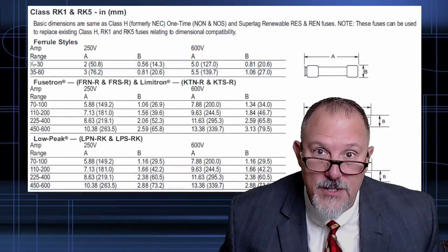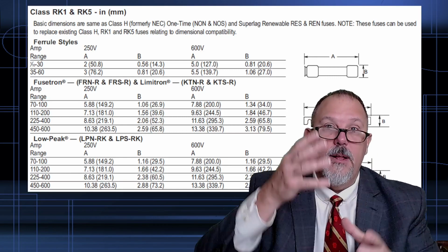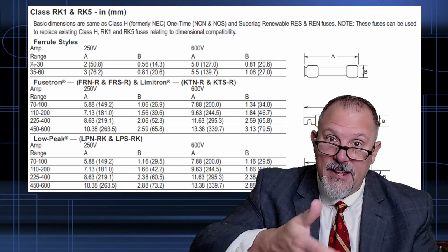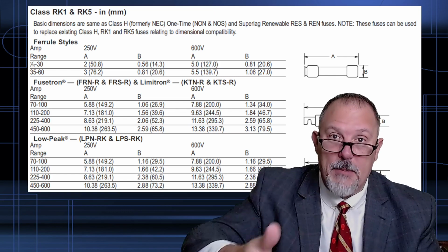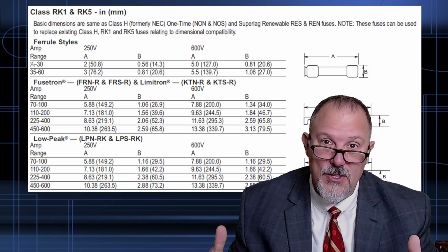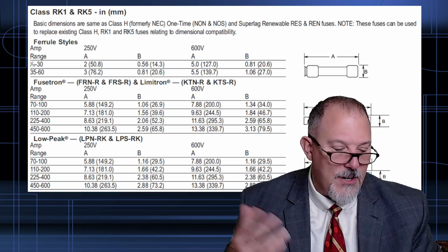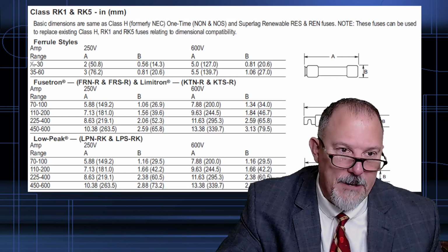So people ask, why is there a 601 amp fuse? Well, that's why. It has to deal with being able to put, say, a 600 amp fuse in a specific application in a piece of equipment that's for a class L fuse. I can't do that. So I may want class L performance. So in any case, that's sort of the logic behind that.